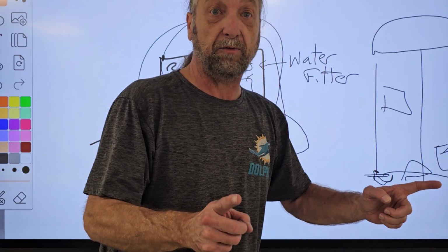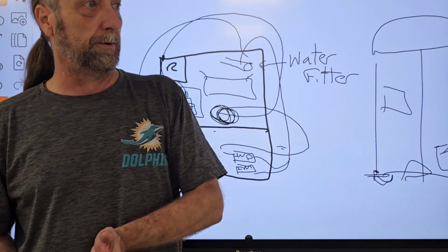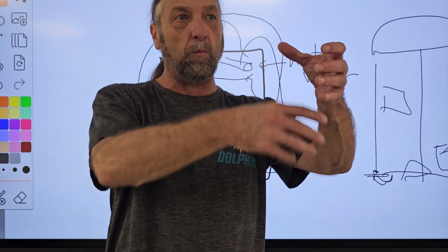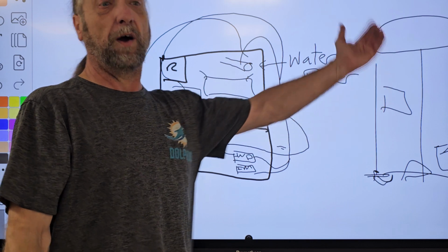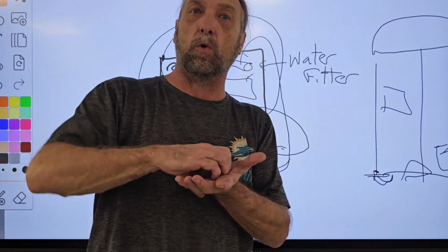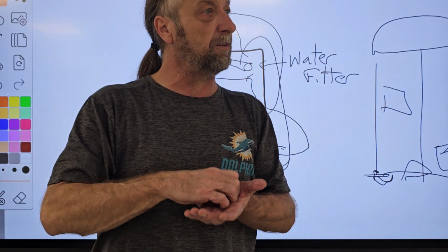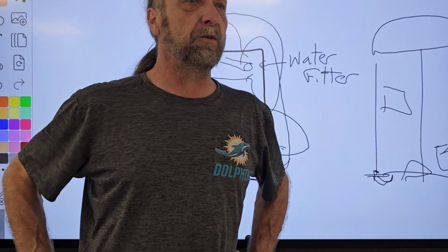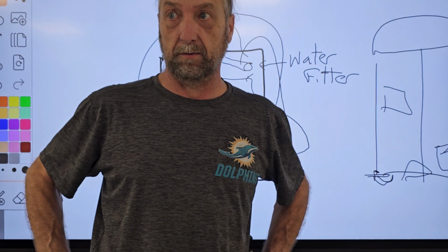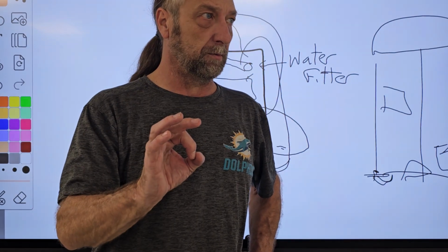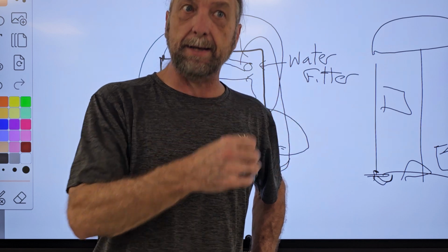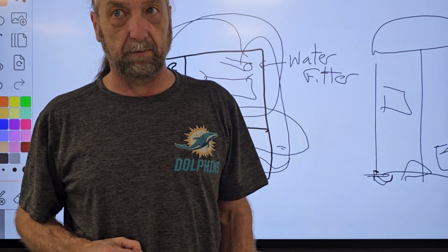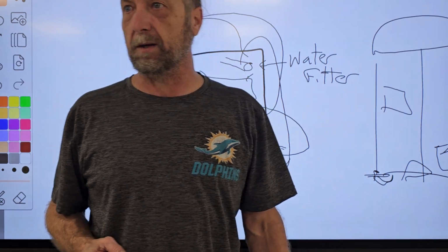So the hose itself has 2 or 3 ounces of warm water. So when a customer puts their cup, they get 2 or 3 ounces of warm water. Then the water from the hose finally makes it and mixes with that warm water. So the customer is going to complain and say, my water's not cold. And it could not be cold. And manufacturers say, listen, this is not a water fountain. This chills water. That's why we have an ice maker and an ice dispenser there, that you put the ice in and you put the water with the ice. Seriously, that's what the manufacturers tell me.